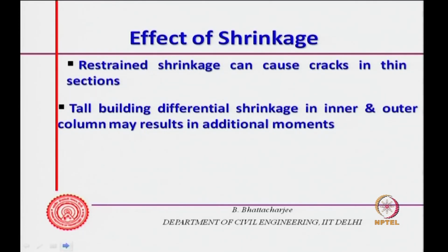High strength concretes are susceptible to autogeneous shrinkage, because you have a lot of cement paste in the system, and therefore, they may be susceptible to shrinkage. So, one has to see that. Therefore, this is studied for low water cement ratio systems; autogeneous shrinkage studies are important.